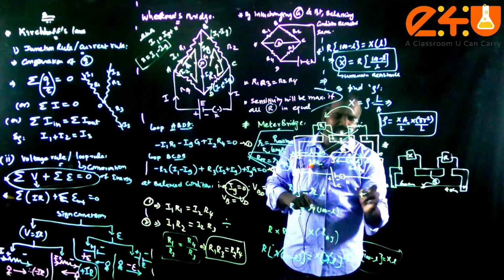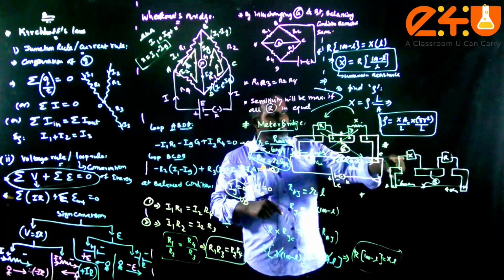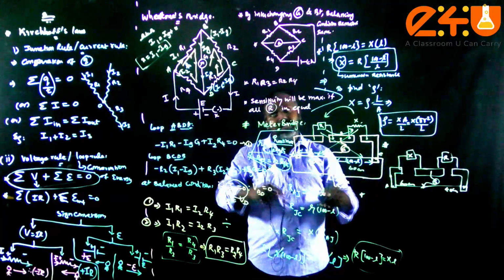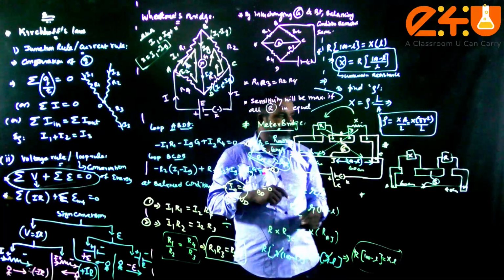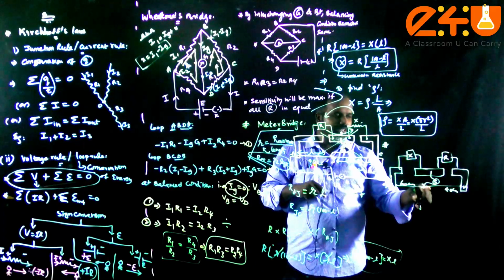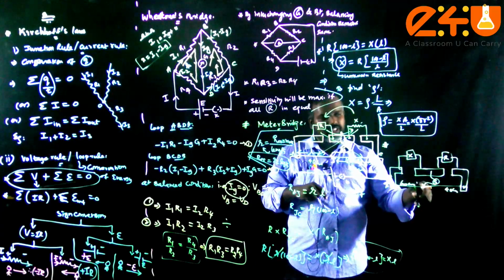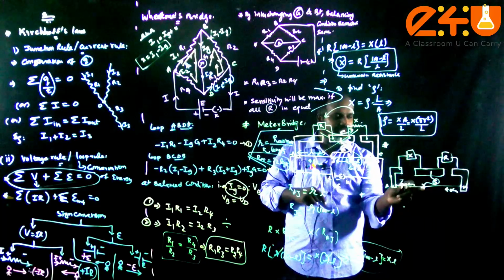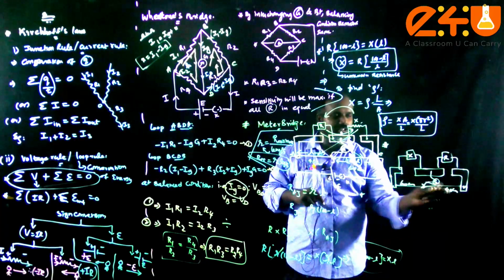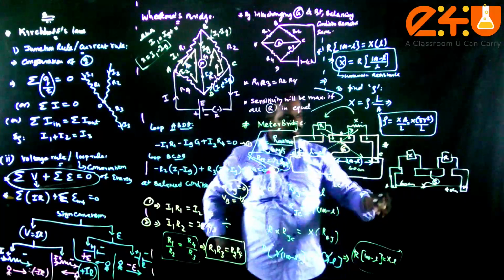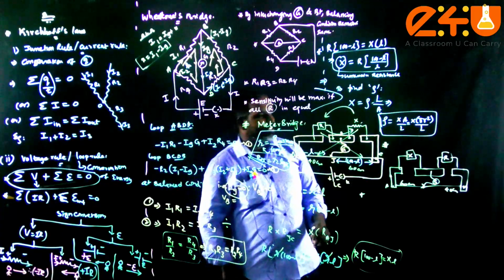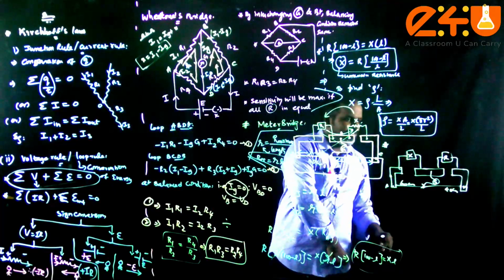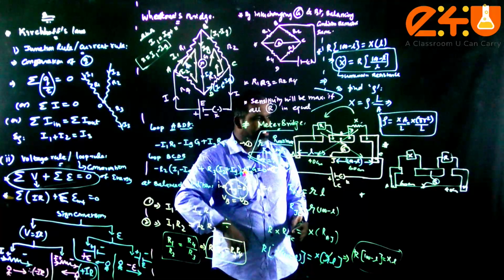And the next point is, as we said earlier, if all these resistors are equal, then there will be maximum sensitivity. Therefore, if you are getting the balancing length at 50, then the sensitivity will be maximum, because at 50 the resistance offered by these two portions of the wire will be the same because of the same length. So this is another thing you must keep in mind for your theoretical discussion.